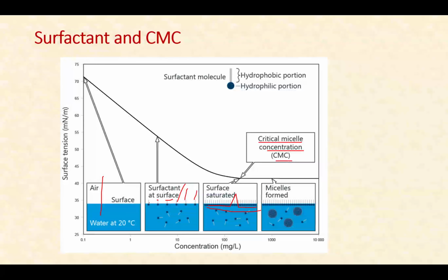What happens if you use the concentration as the CMC, the critical micelle concentration? Through adsorption, some amount of the surfactant will be adsorbed on the rock surface and lost. Then the concentration will be reduced, and you will get much higher values of the surface tension or interfacial tension. So that is not desired. Accordingly, you have to perform some study, that is, the adsorption study.